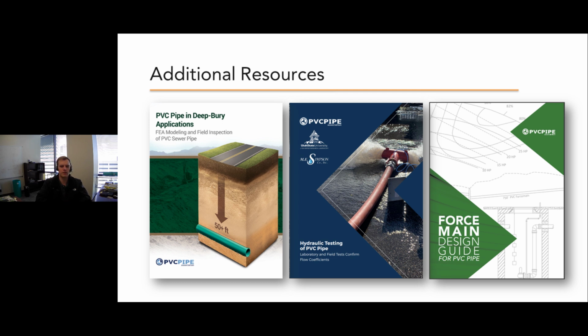And that kind of expanded on previous research and contained a whole lot of new research on cyclic testing and lifespan based on number of cycles and pressure fluctuation during these cycles as well. Mostly it's important during force main design, but it is applicable to other cyclic designs as well. If you're in an area with high pressure fluctuations or a lot of occasional and cyclic surging and stuff like that. So I cover the West.